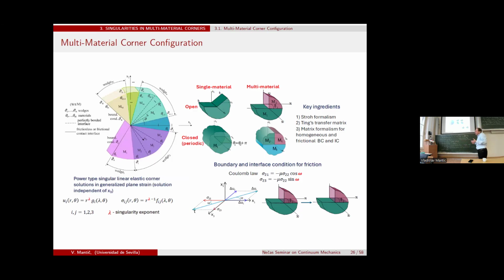In this case, we are also developing a semi-analytical procedure, which provides arbitrary accuracy, if you like. Of course, we will also use Stroh formalism, but in a slightly different way. Stroh formalism is basically the formalism which gives us the way to compute the solution in anisotropic materials under generalized plane strain situation, which we call 2.5 dimensions, something between 2D and 3D.